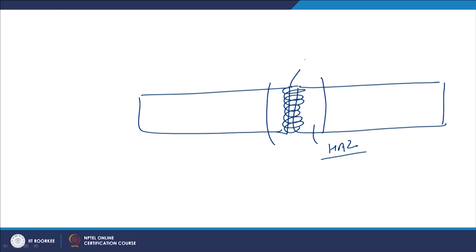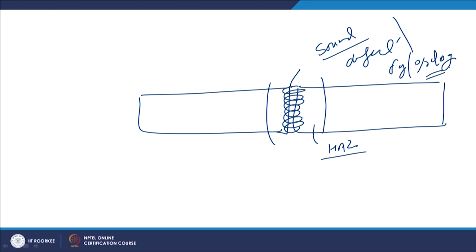In this case, whether the joint being formed is sound and free from defects will depend upon the yield strength and the percentage ductility or percentage elongation of the metal. Higher ductility, greater elongation, will lead to easy development of a sound weld joint, free from defects, with the minimum energy requirement and the minimum possible effort. But still some amount of heat affected zone will be developed if a little heat is generated, and if the heat generated is negligible, then the HAZ will be absent.